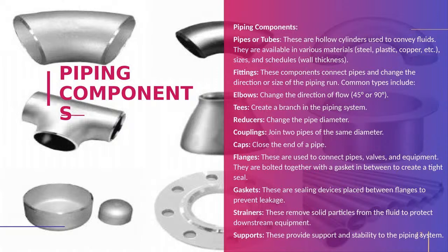if it is handling semi-solid fluids, it requires frequent maintenance or cleaning of the pipes. So in those areas we will be using flanges. There are also different types of flanges according to the services, which we will see later.